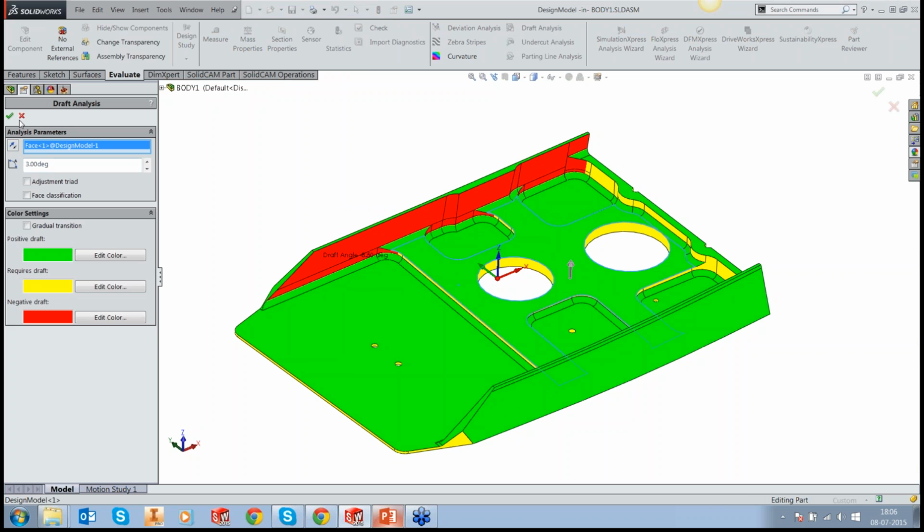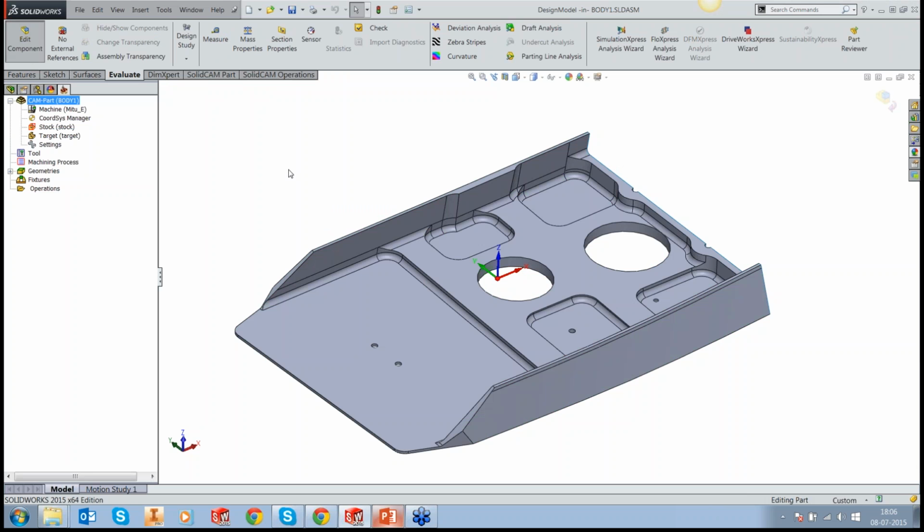Okay. Now this could be machined using our positional 5-axis. That means I could tilt this part and cut it, but that will need another attachment. It would mean to invest $100,000 or more into some machine which is already having this attachment, or buying that attachment. If the part is too large, then you can't put it on the attachment. You need to have that particular machine.